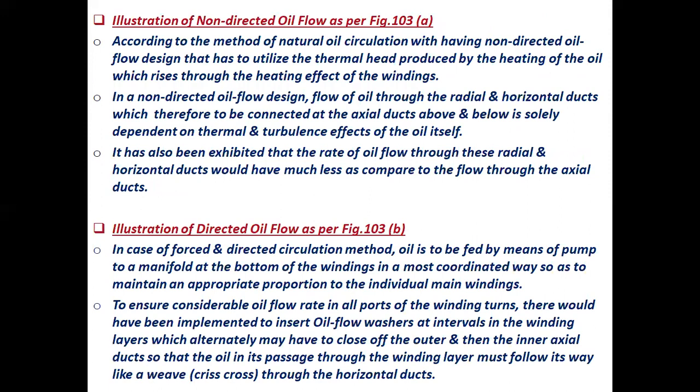Illustration of non-directed oil flow as per figure 103A. According to the method of natural oil circulation with non-directed oil flow design, it utilizes the thermal head produced by the heating of the oil, which rises through the heating effect of the windings.